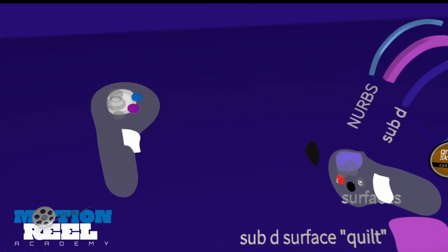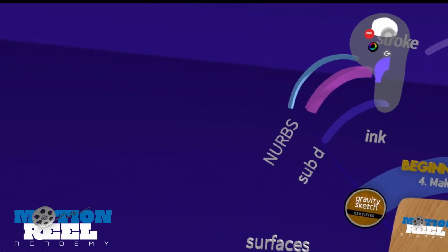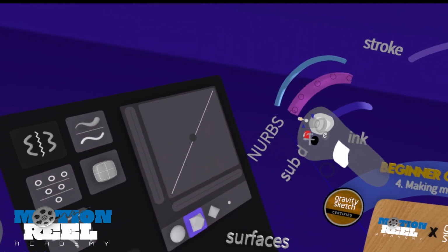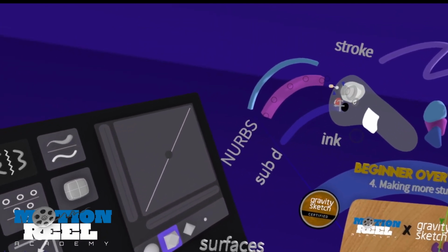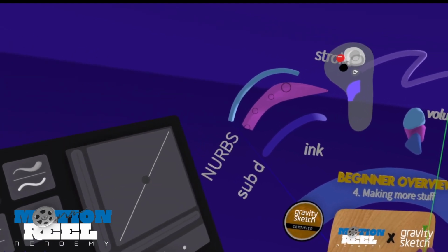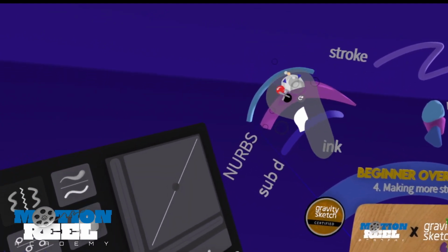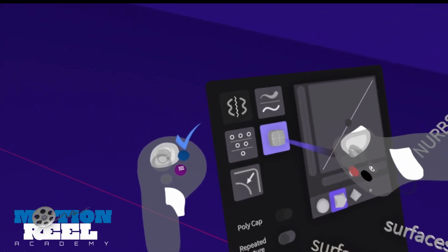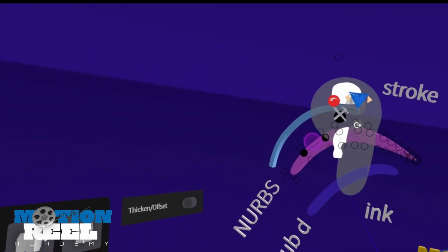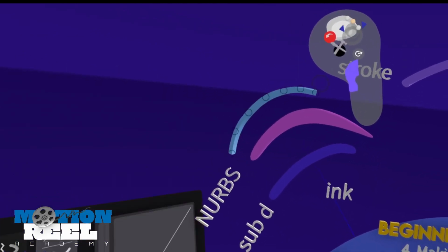When you draw with the ribbon tool, this is actually Sub D geometry. Now I can take this and turn it into Sub D. So you can see this is just one line creating this piece of geometry, and I can make changes to this line and it will change the geometry, and that's how NURBS works. It works with just the one line. Now when I turn this into Sub D, you'll see that it's a bunch of squares. So I can't modify this any longer the way that I could when it was a NURBS object.